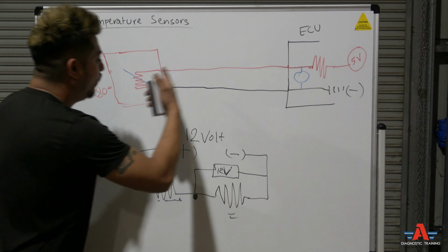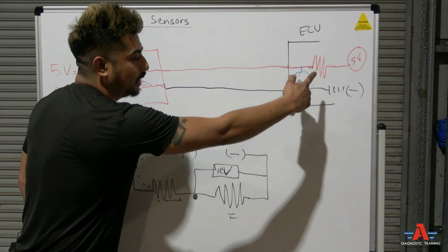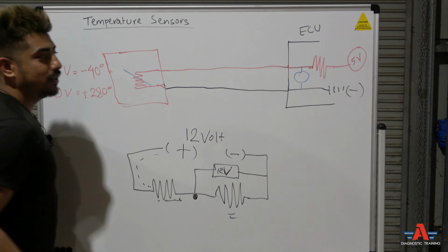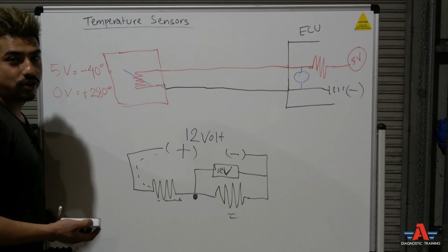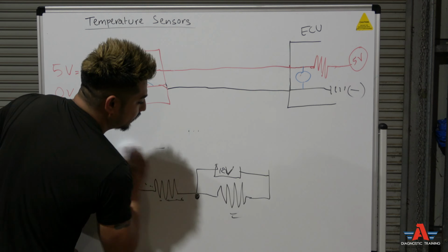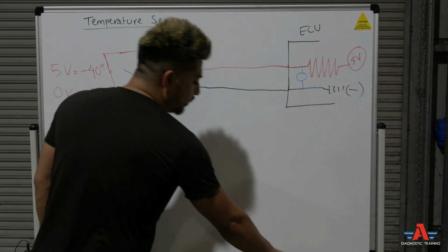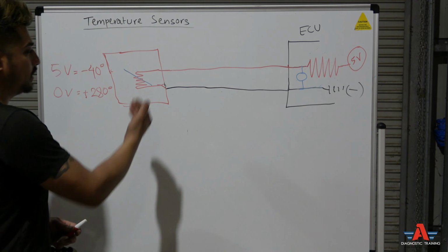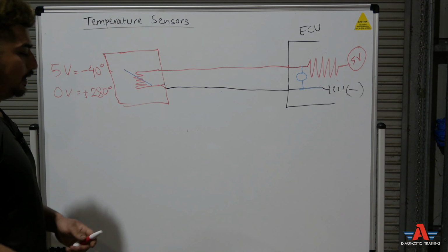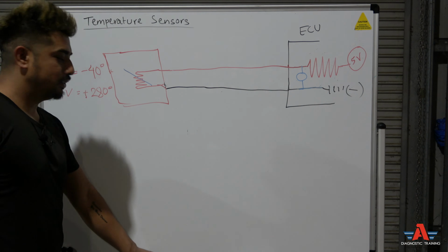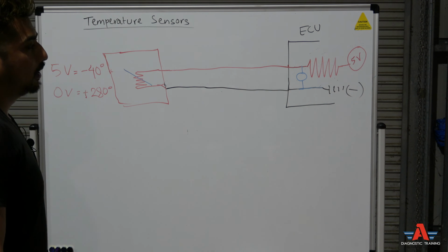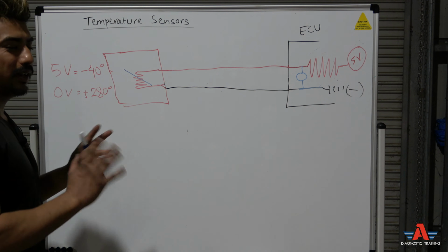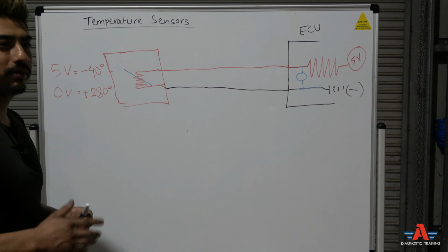If there is no resistor, if this sensing circuit is not in between the two resistors, that sensing circuit is not going to see the changes in voltage. Now we understand the basic principles, what's happening inside the ECU and what's happening inside the sensor. It makes it very easy to diagnose this sort of problem. A lot of the time it's a very simple circuit. You can diagnose this sort of stuff within 5-10 minutes most of the time.